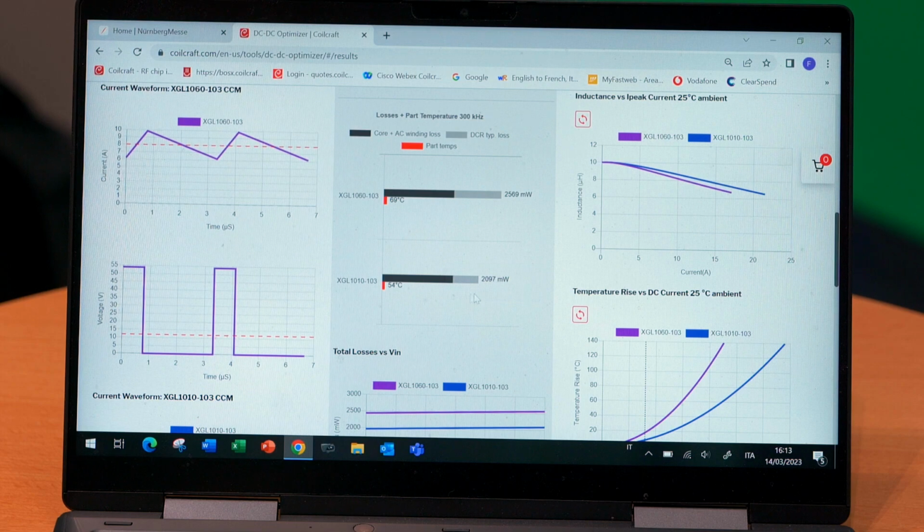And as you can see, the different impact of the DC losses for a smaller height part. You have higher DC losses, higher resistance of the copper wire, and that has this impact. It's about 0.5 watt more. This is quite significant. Yeah, exactly. But actually, an engineer needs a number to decide if sacrificing, losses, 0.5 watt more, would allow the 6 mm tall part. So you have to judge like that.